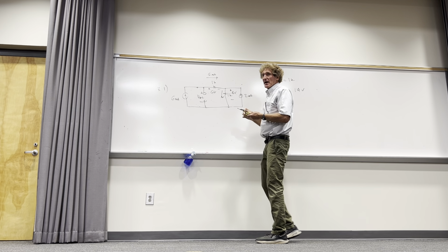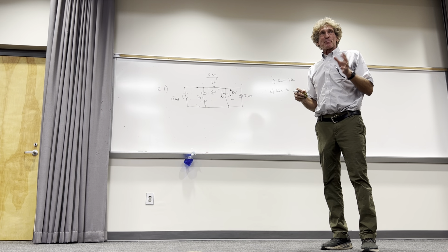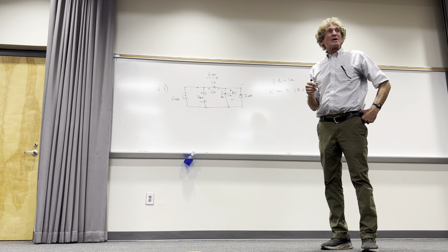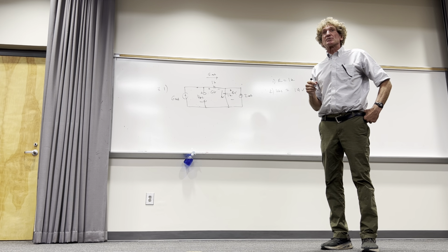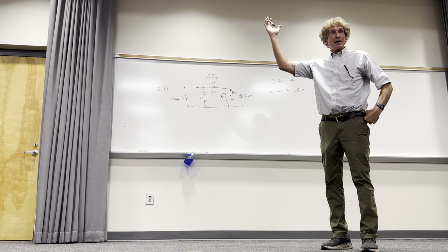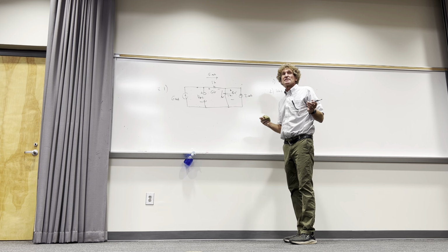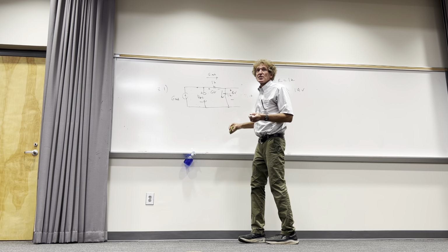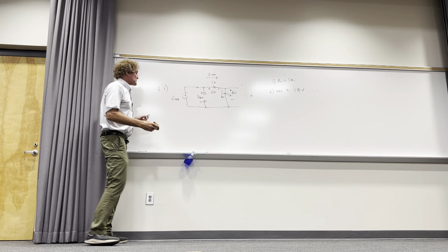Believe it or not, I think that is the very problem somebody asked me about. I don't know who it was, but I got this email. I tried to answer. You with me, class? Now I have that. What's the next thing I do? Anyone? Turn off the sources, right? How many remember that? Turn them off. All right, they're both current sources. What do we do to them? I erase them. You cross them out. They are not there. When you turn off a current source, it's like cutting the thing out of the circuit. With me? So I'm just going to erase them.